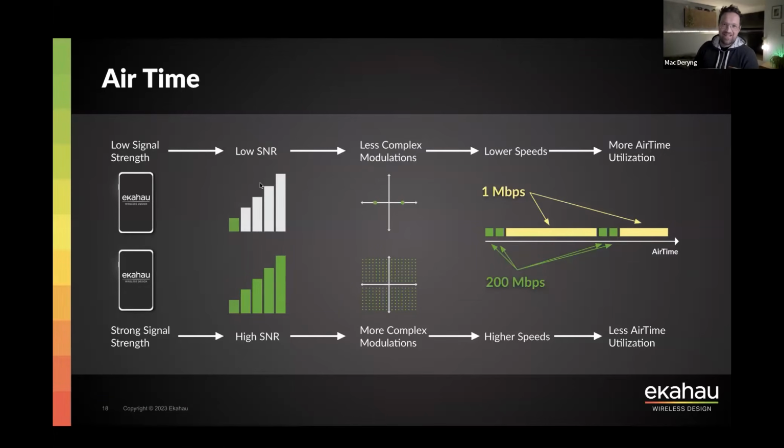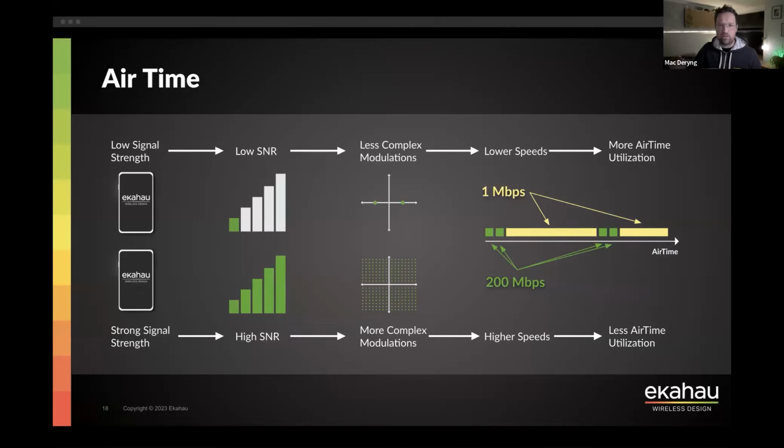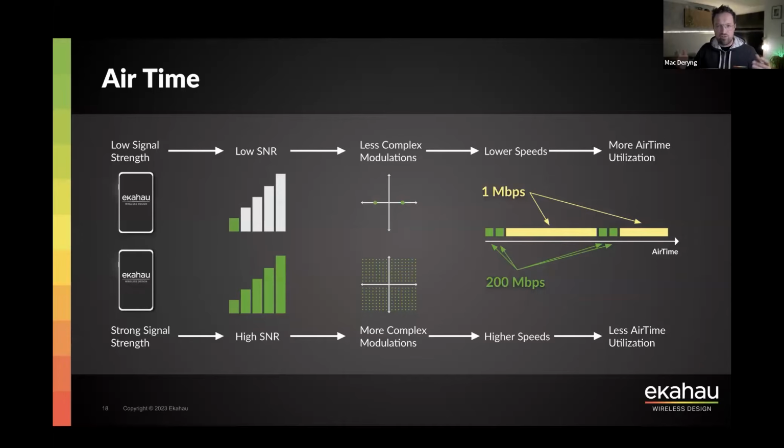Okay, guys, so when you have low SNR, so either a low RSSI, low signal strength that your device has received a frame with, or high noise or high interference in this particular time where the frame was received, you will have low SNR. Or you can have a combination of both, not too strong RSSI, fairly strong noise. Anyway, your SNR, signal to noise ratio, is low. And when your signal to noise ratio is low, it means that the usable signal that is being transmitted by a transmitter is of a low quality.